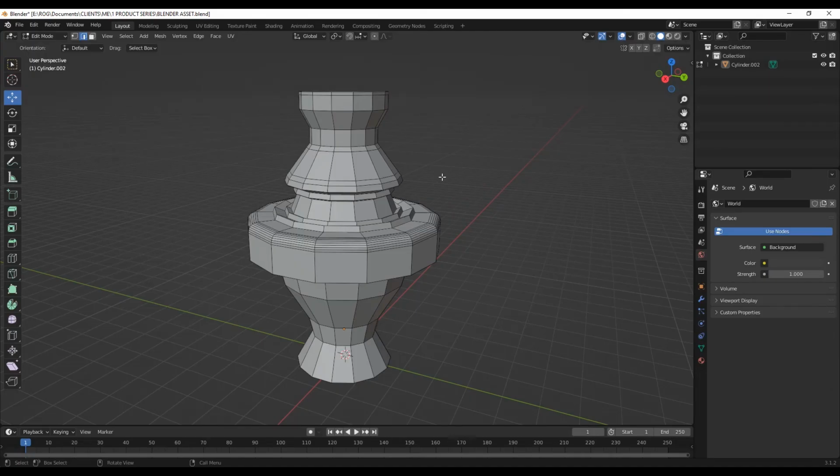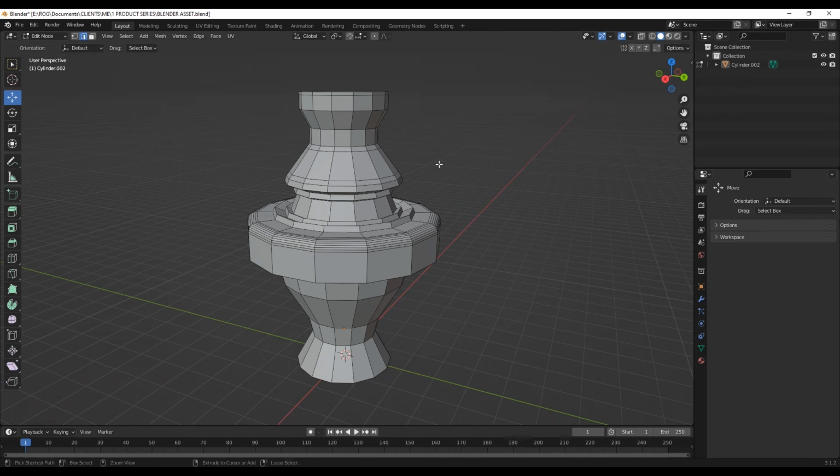Another good thing to note when modeling is that when you use a tool on Blender, you can also adjust the settings from the properties. So let's go to our tool properties here and keep this active. So let's practice this with our loop cut. So if I make a loop cut here and I just left click and then also left click again to drop it. If I go down here, I can bring this menu up and then I can adjust some settings. So if I increase the number of cuts here, you can see that affects the cut we just made. So you can always check the settings here for whatever action you make.